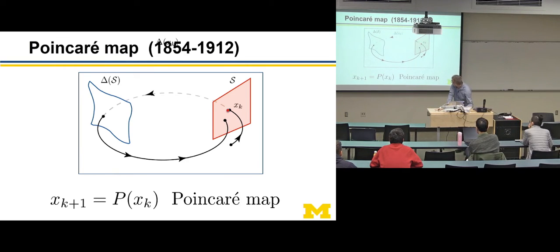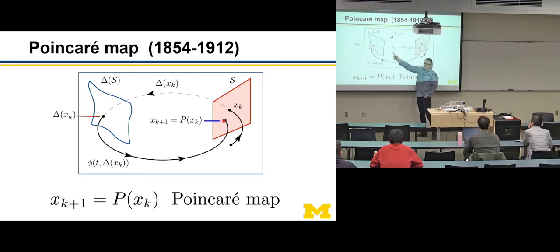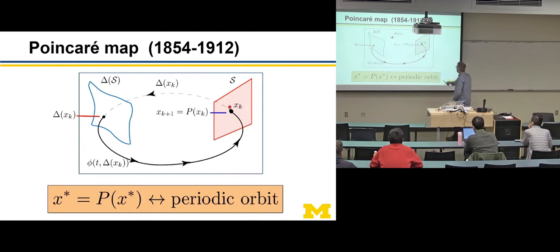And so the Poincare map does this. You start out with your initial condition. There's my jump from the impacts. I now follow Lagrange's equation and my feedback, and I come back around. And so that's xk, and that's xk plus 1. So guess what? If I start at a point and I come back around, that's an equilibrium motion for my robot, but it's a fixed point for this mapping. So now you know a physical fixed point, okay? An equilibrium point of a Poincare map.